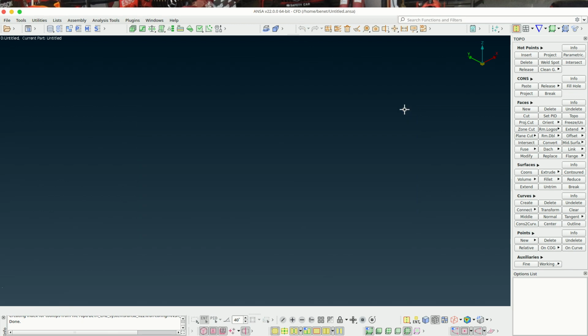So afterwards, we have some, well, we can say additional tools that most of them we are not going to use. For example, we have scripting, so we can automatize all our processes with Python scripts that work with an Ansa Python library. But we also have, for example, here batch mesh. That's a tool that we are going to use for meshing when we get into the driver or for when you do the aircraft project.